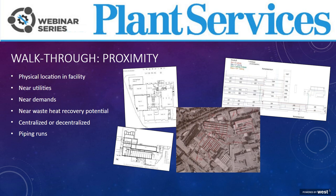Not only should the compressor room be big enough to house all of your compressed air equipment safely and with sufficient service access, like we just talked about, but you should also consider where in the facility those compressors are located. Normally, your compressed air system is going to be installed near other major utilities such as power, water, and gas. Keep in mind that your compressor has a significant amount of recoverable heat, either through space heating or water heating, and therefore, if you have a process in your facility that could benefit, it may be advantageous to locate your compressor room near that process.